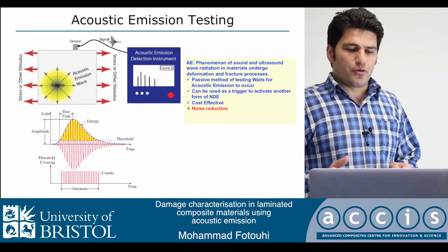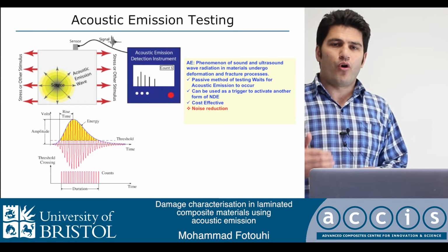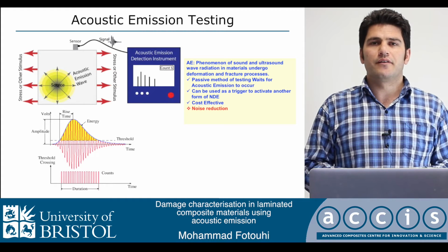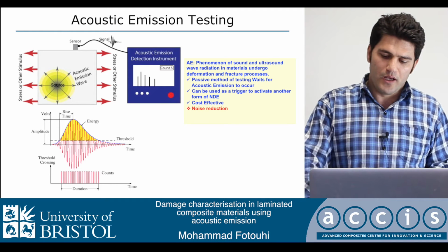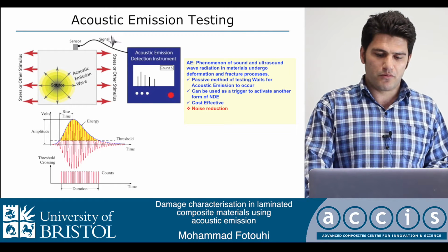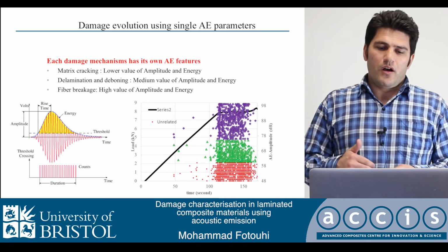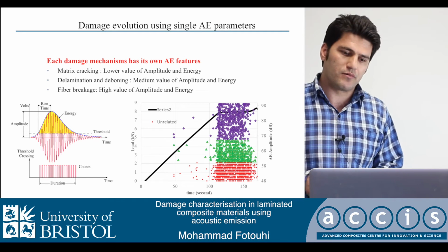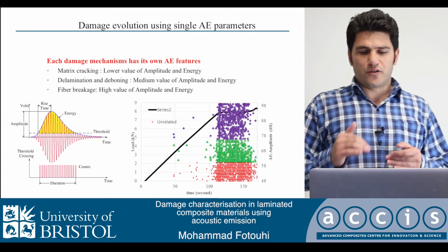This method has some benefits, but besides, we have a problem in using it about noise reduction and the analysis of data, which are very important to have a good analysis of our structure and our damage mechanisms. We tried to separate different kinds of damage mechanisms using different techniques with acoustic emission signals.